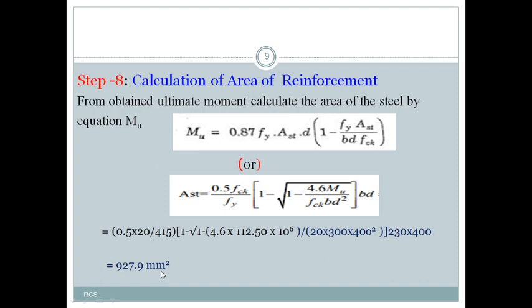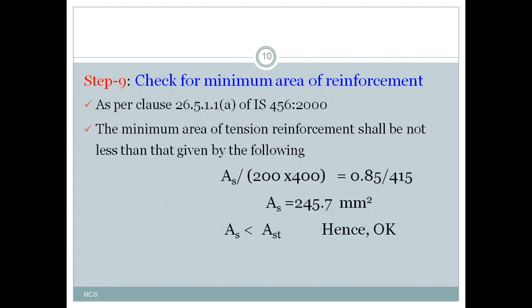Alright, now with this we have calculated the parameters required for the design or construction of your cantilever beam. So what are those parameters? B is the width, D is the effective depth, and AST, that is the area of tension reinforcement provided in the beam. Right, whether the obtained values really fulfill our criteria, or whether they are really safe against the load applied. So for that we have to go for checks. We have some checks here according to the IS 456.